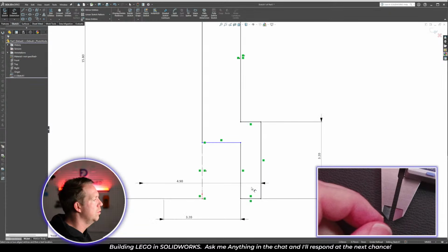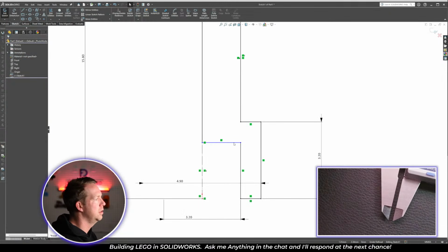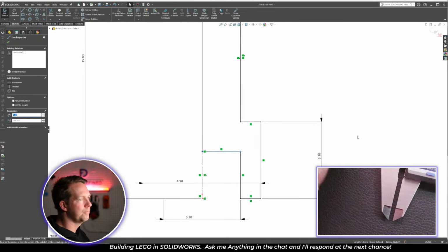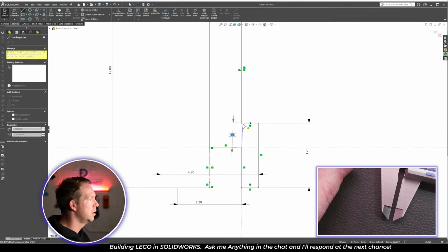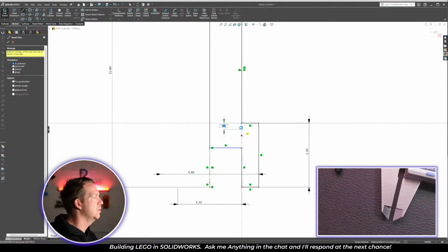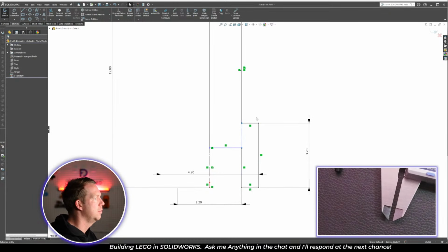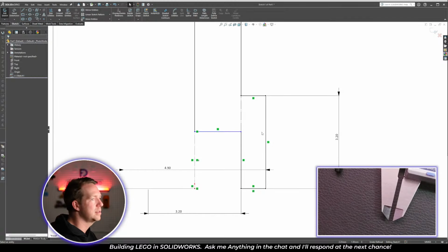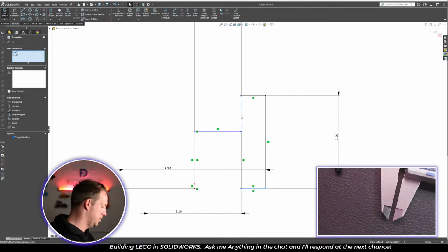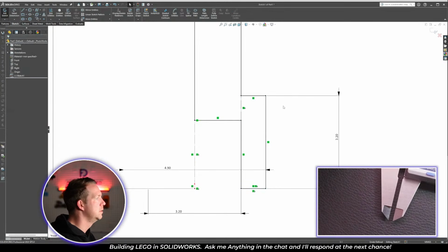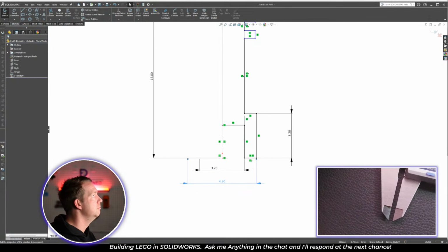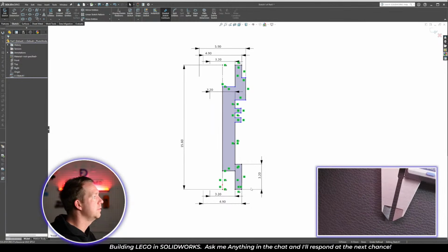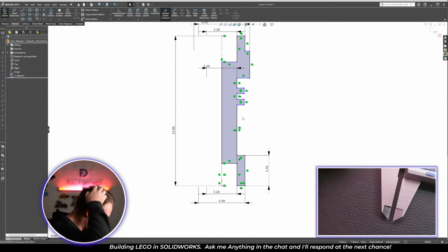And if we look at the wall thickness, so one way that we can dimension the wall thickness here, it's probably going to be a consistent wall thickness with what's on the outside. By what I mean is this section here, this thickness. So I'm going to select this edge and this construction line that I've just put in and make them equal. That gives a consistent wall thickness through that area. All right. If I turn on shaded contours, you can see a bit more clearly what we've done.